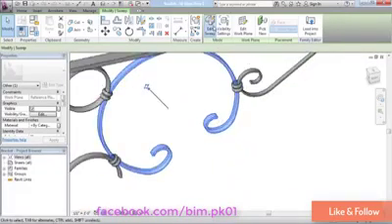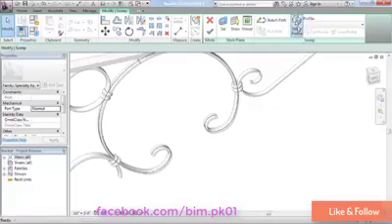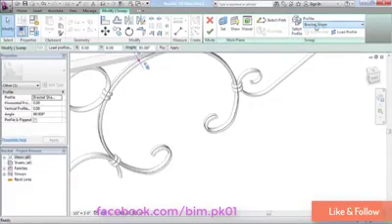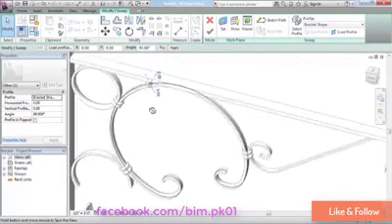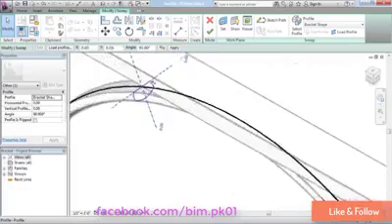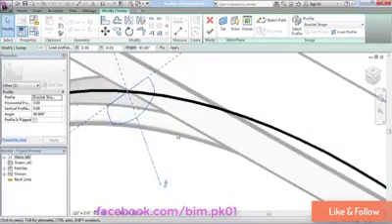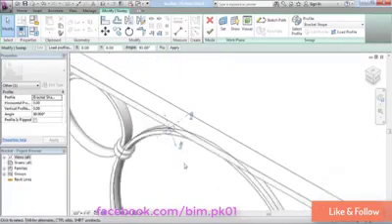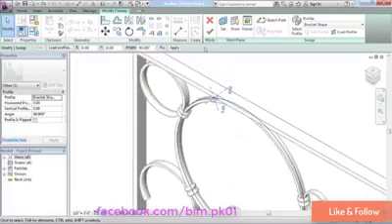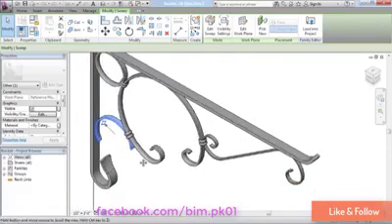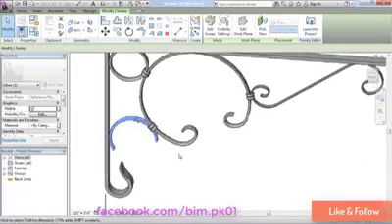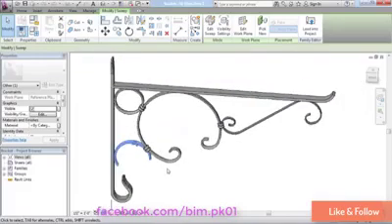That one is using a profile. So when we click on select profile, there's a profile here called bracket shape, and so that's a nested profile family that's been loaded in. Kind of spin the view around right there. You can get a better look at it. Sort of looks like that. The advantage of using a profile shape there is that that same profile shape can be used for other sweeps like this one, and it can even be used in other families if you wanted to. So if you were going to create several versions of this bracket, you could reuse that profile.